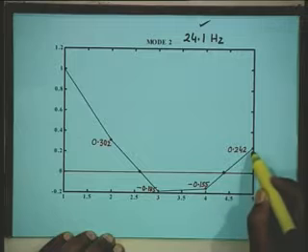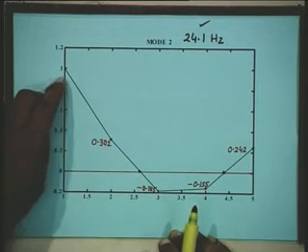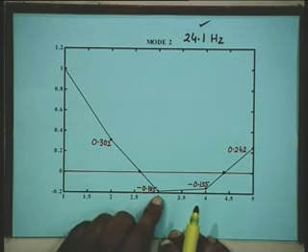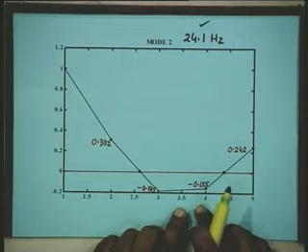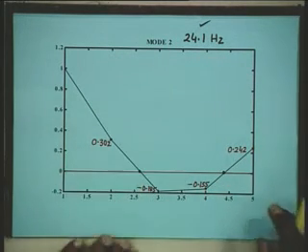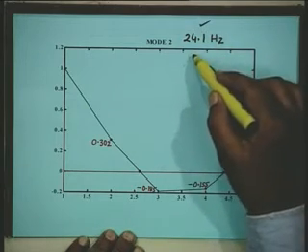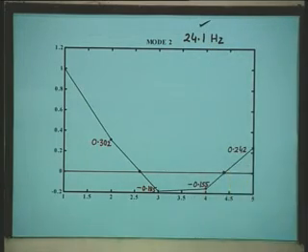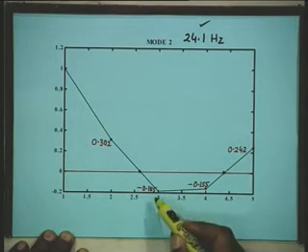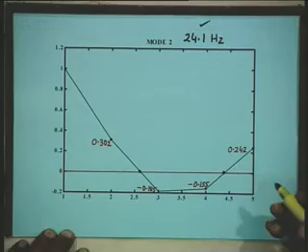Okay. Now, in this, when you try to analyze here, then you can easily understand that these two masses 1 and 2, these masses will oscillate with respect to the masses 3 and 4, and similarly the 3 and 4 will oscillate with respect to mass 5. That is, whenever it is disturbed or perturbed with the frequency corresponding to this 24.1, right, the shaft will oscillate in such a fashion, so that the mass 5 will oscillate with respect to 3 and 4, and 3 and 4 will oscillate with respect to 1 and 2, right, and frequency of oscillation is so much.